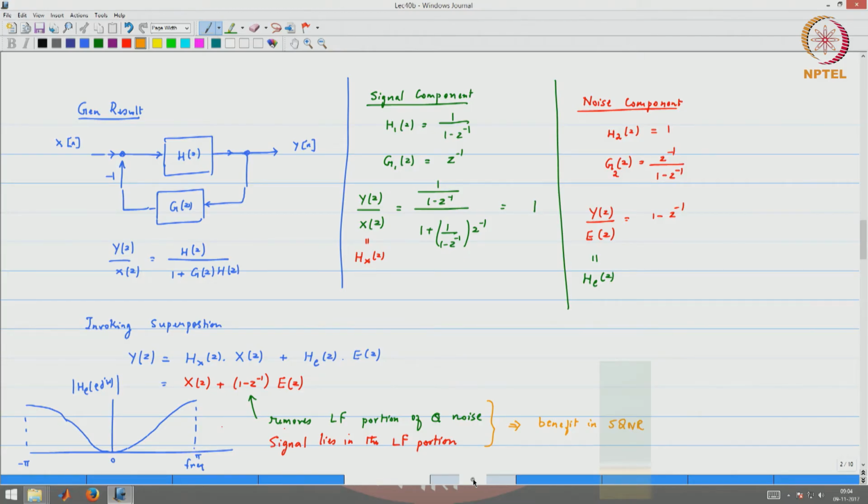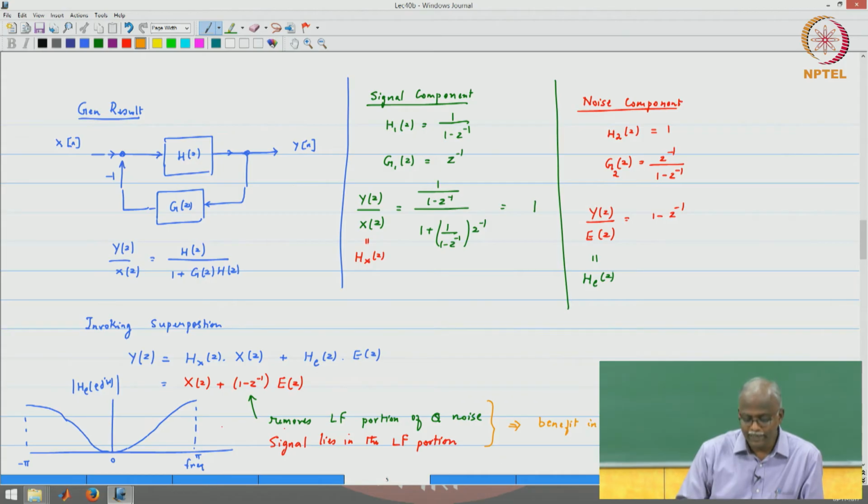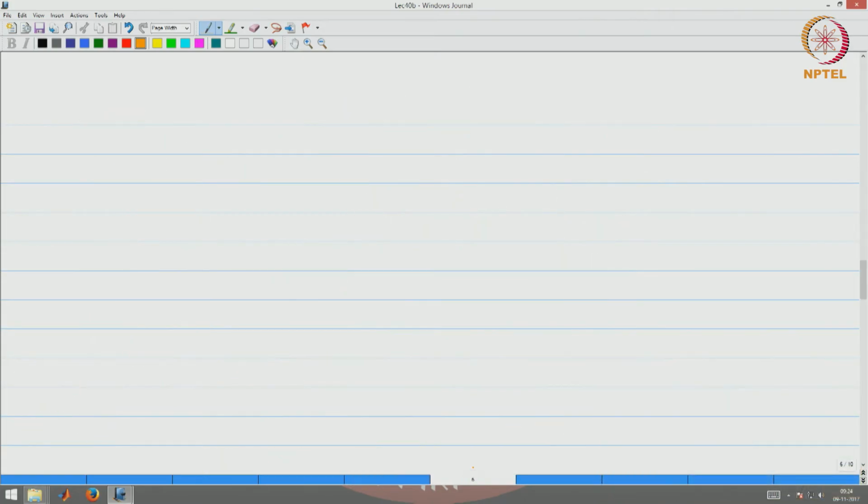And so, is this okay, what we have done? Basically analyzing the transfer functions, showing that the output is the input x of n plus a transfer function times E of z. So, here is an equivalent diagram if you would like to draw it down. The continuous time signal x_a of t passes through a C to D converter, oversampled.